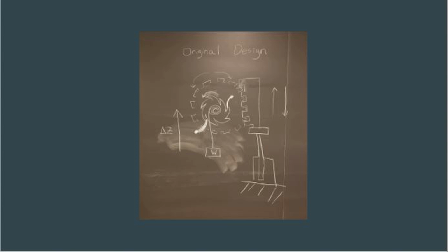We initially made a ratchet and pawl mechanism. The piston had a rack attached to it vertically. As the piston moves up, the rack moves up and turns a stationary pinion. The pinion gear is attached to a ratchet gear. Two pawls are lined up with the ratchet so that it can only turn in one direction.